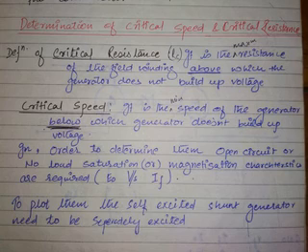Carefully observe one thing. If you want to plot E0 versus IF, let us say IF is 1 ampere. Take a simple generator where the maximum IF value is 1 ampere rating. So E0 on this axis in volts. You require IF 0, IF 0.1, 0.2, 0.3, 0.4, 0.5, like that, different values. For different field current values, what is the amount of voltage? This is what the curve is telling you.